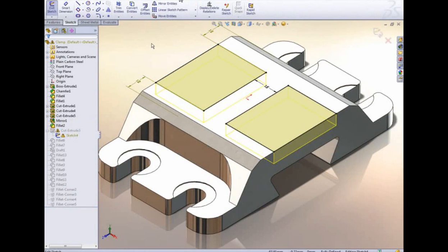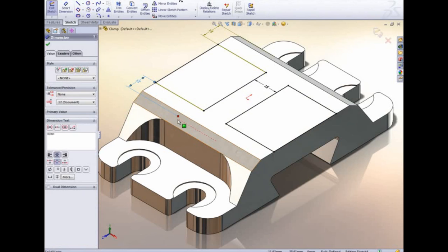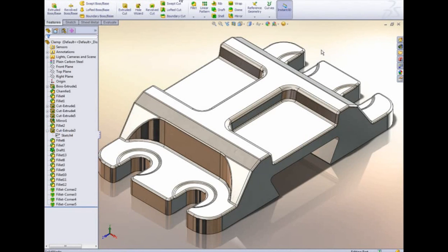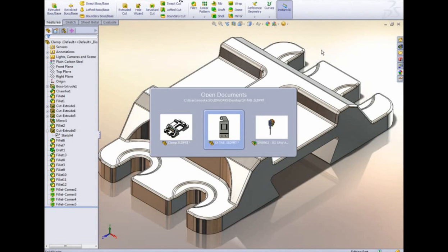If we edit the sketch, the brown coloured dimensions are a problem, as they are dangling in space. Selecting them highlights where the edges used to be, a great way of remembering what was there before. Again, we'll just drag and drop them onto another edge. Now we can go home. No, wait, there's just one more thing, the Mate Expert.